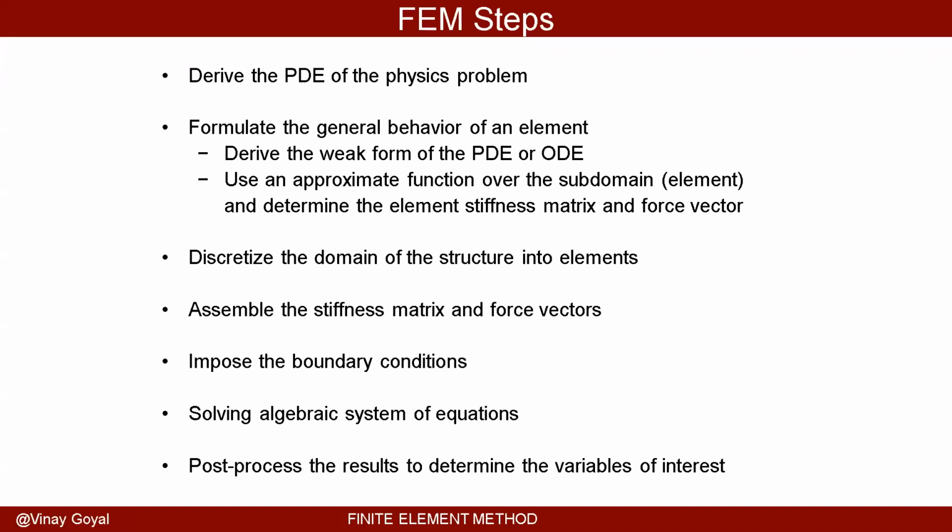And the idea there is to break up the problem into pieces where we can actually now solve the equations a little bit easier in a more simple domain, and then bring everything together and assemble it. And the way we learn how to do that is to formulate the element behavior, deriving the weak form of the partial differential equation. We use an approximate solution over a domain, and it will be an element.